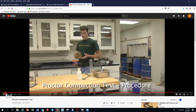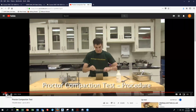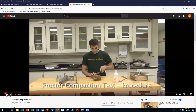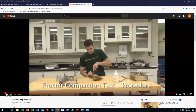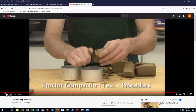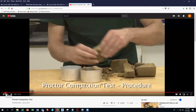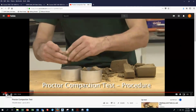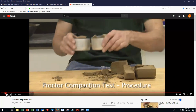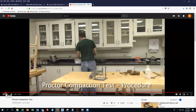After the sample has been extruded, split the sample with your knife. Take samples from the top and the bottom and place them in the moisture cans for moisture content determination. Weigh the cans on the scale and record the weights.